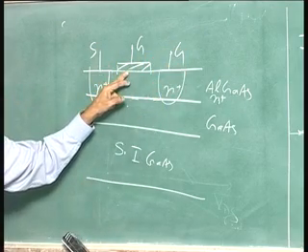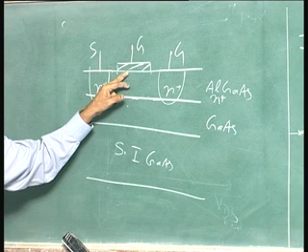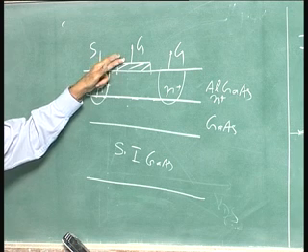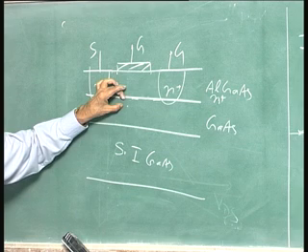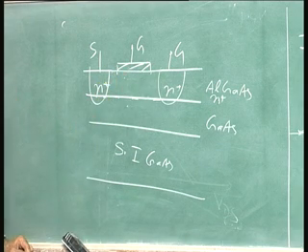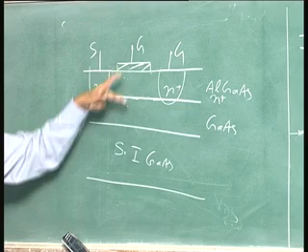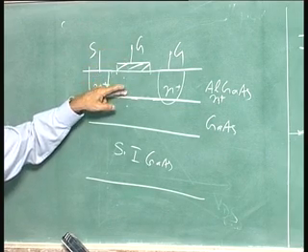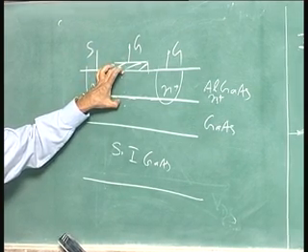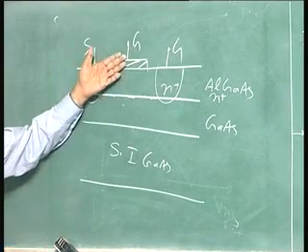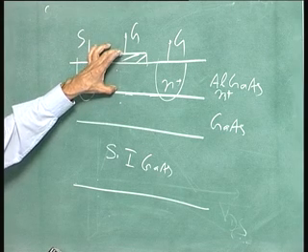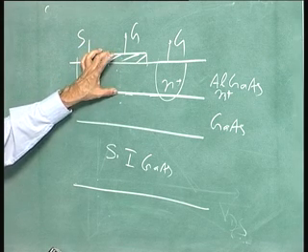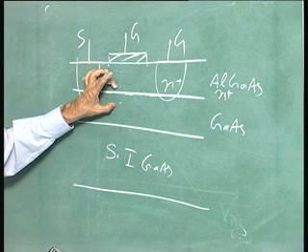I keep on making it more and more positive. Okay. What happens? You keep on making more and more positive, of course, you have more and more electrons here. But at a point, what will happen to the depletion layer of this? See, there should be a minimum voltage across this layer, negative with respect to this substrate, so that the entire layer is pinched off. Now, you keep on making it positive. See, if I had only this particular layer, VBI minus VP0 is the voltage that is required to pinch off. Okay. And I need a certain voltage to remove these charges here.